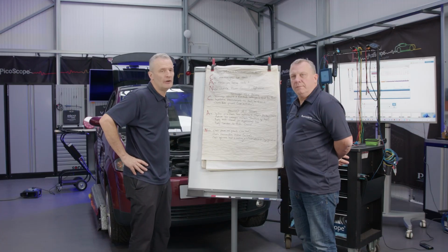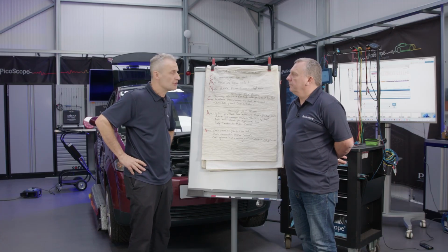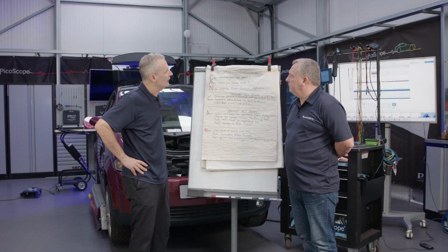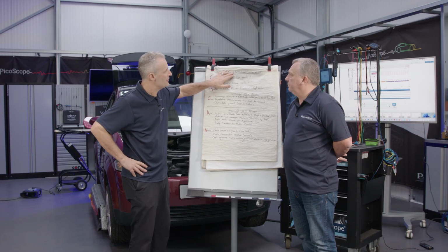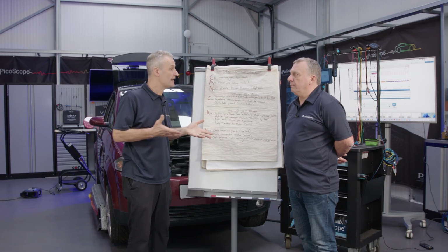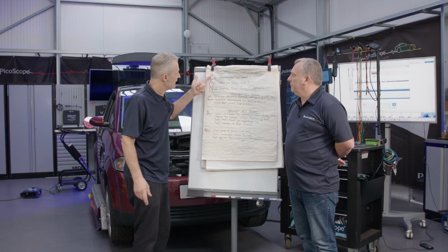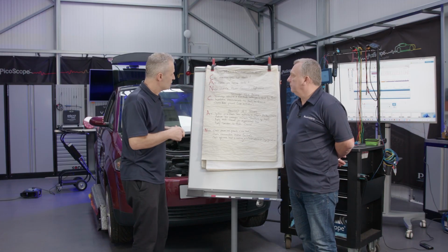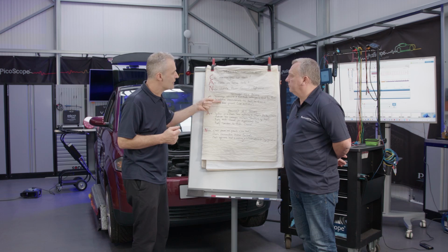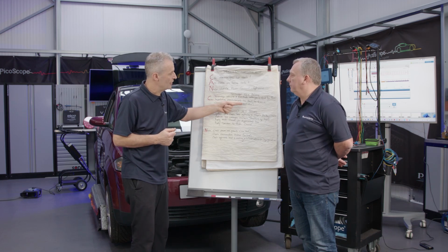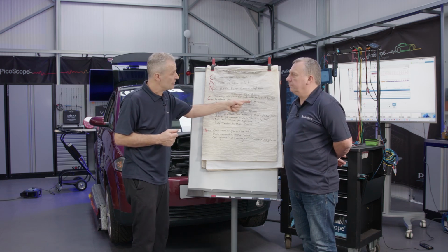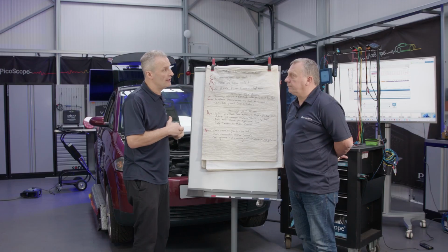Okay, so we're going to summarize here exactly what we've just covered in those previous videos, and that is, let's say for example we've got a DTC communication error on a network, not necessarily CAN. Let's follow this CAN process. Can CAN messages be sent? That's where we were looking at things like the impedance of the network, the short to ground.